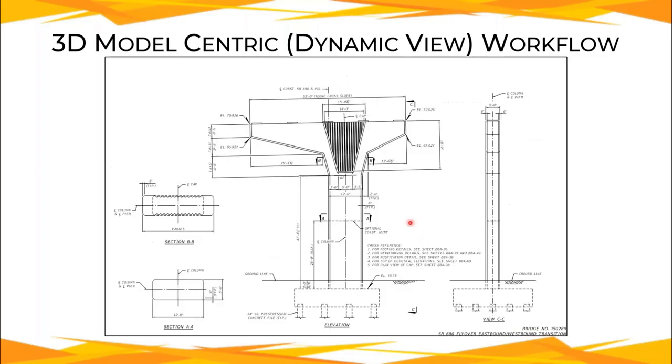Last example here is going to be one like this, where we have section cuts within section cuts. So we're going to use a view here, like a front elevation view, and then we want to cut through that front elevation view, which is a 2D drawing model. But we can do that because the program knows, when I create this front elevation view first, that it's created from a 3D model. So if I go into the drawing model of this front elevation view and do a section cut through it, it's going to create these sections for me here.